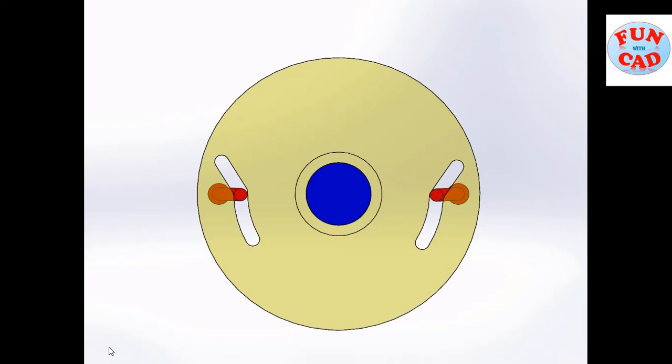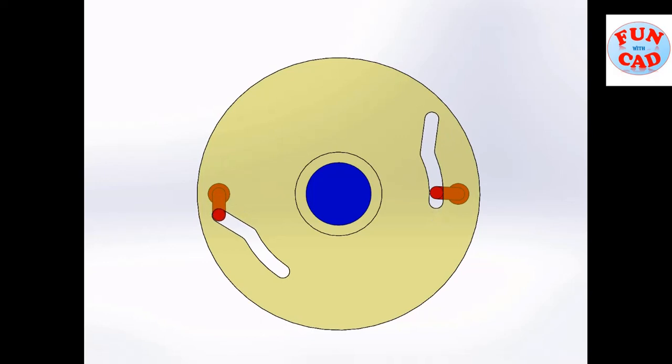Hi everyone. In this video we will see how to make trajectory on rotating dial for toggling the switches, and visualize using motion study tools in SolidWorks 2017. Here, 25-degree rotation of dial on either side turns on the respective switch without affecting other switch.